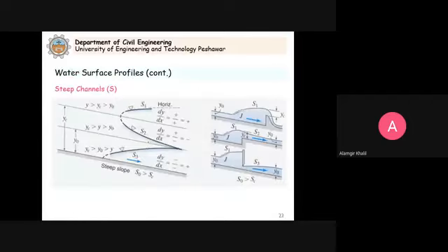Now let me go to here, we discussed this in water surface profiles. We have S1 because the depth is above the 2. It is above the critical depth and it is above the normal depth. So S1. If it was between the two, S2. Below the 2, S3. Now in this case, if this is going to occur, you have, let's say, the normal depth, then you have the hydraulic jump, then you have the S1 profile.